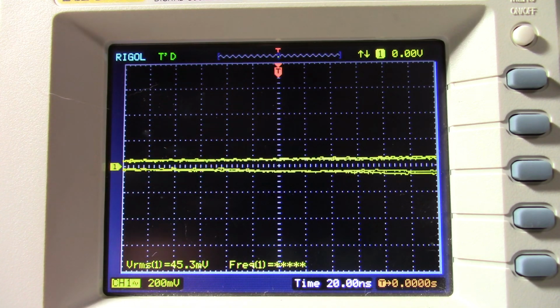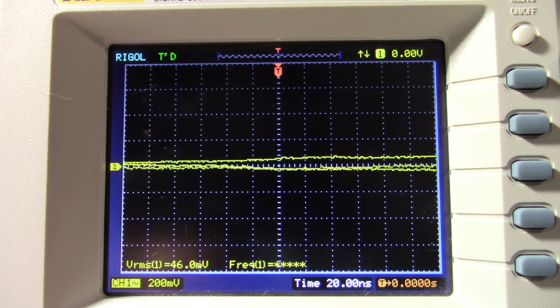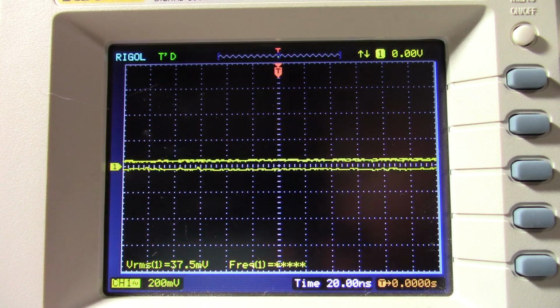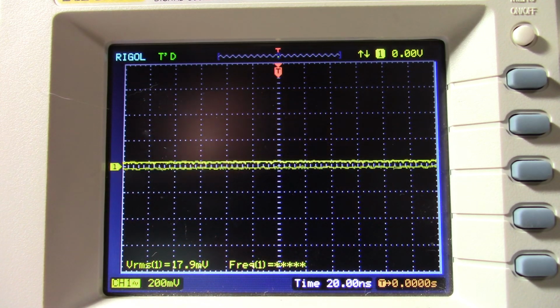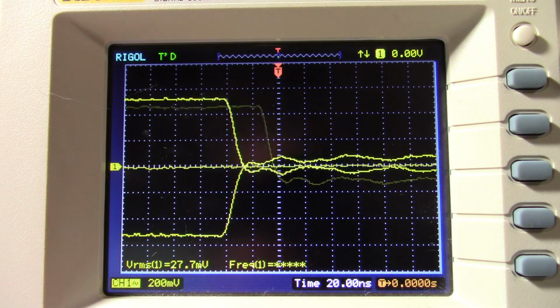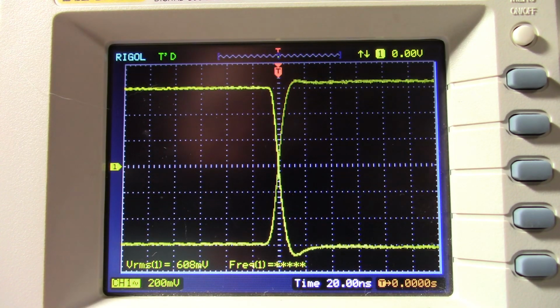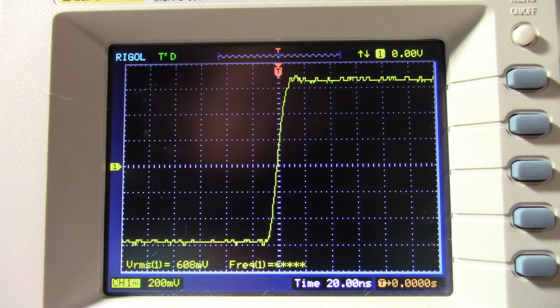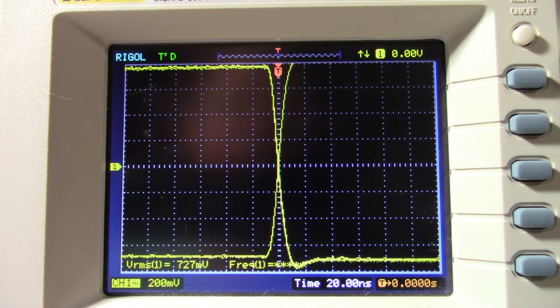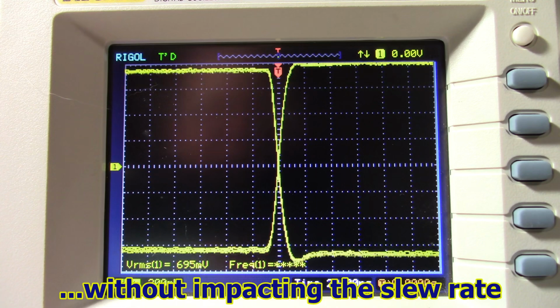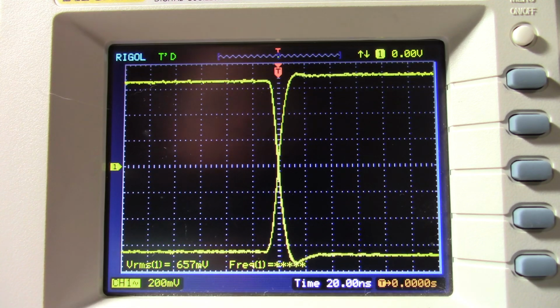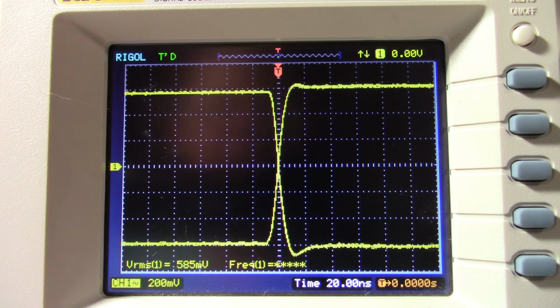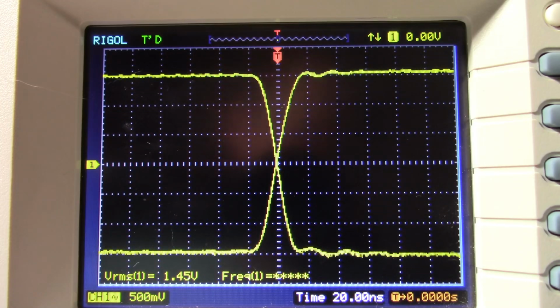You know, at that signal level, maybe I should switch back to the 47 picofarad cap, see if that's better. Yeah, I think I'm going to run with that because this is more of the signal level that's going to go into the amplifier. And that's even better. Still getting that bump down there on the bottom. There's not much I can do about that, I'm afraid. But yeah, this is pretty good.